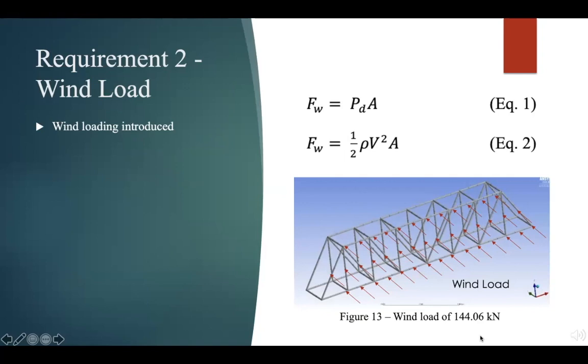The area used for calculation is the bridge wall of 16 meters by 3 meters, producing a 144.06 thousand newtons wind load for simplicity of the calculations, which is an overestimate but helps to provide maximum deflection. If the actual area of the contact is calculated, the force acting would be much less, causing less deflection, improving the structure's stability against wind loading.